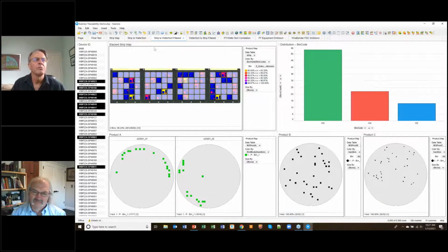Actually, before I go into that, let me talk about what we're looking at here. This package is made up of a large device on the bottom from product A, and then there's a smaller device from product B, which is placed on top of it. Then it has 3 smaller devices on top of that from product C. Below, we see product A, and we see an edge pattern emerging. That may well be the root cause of why this final test fail started to take place.